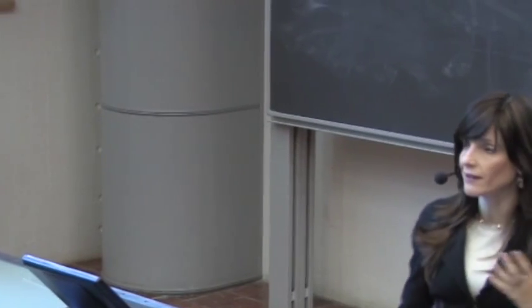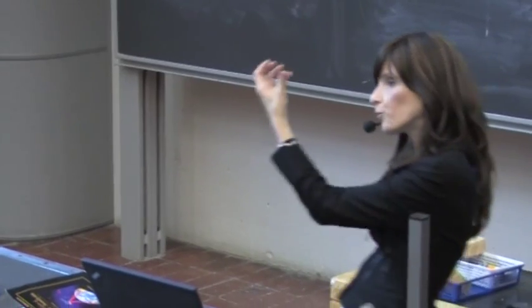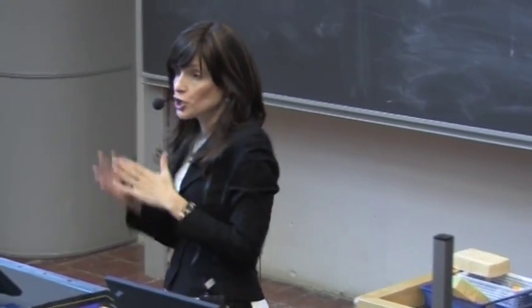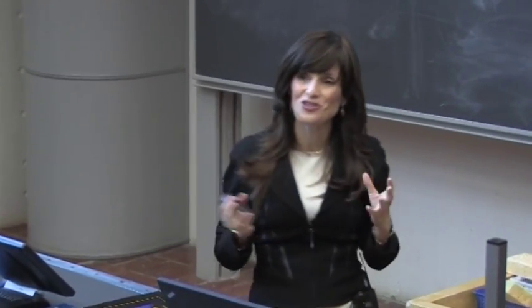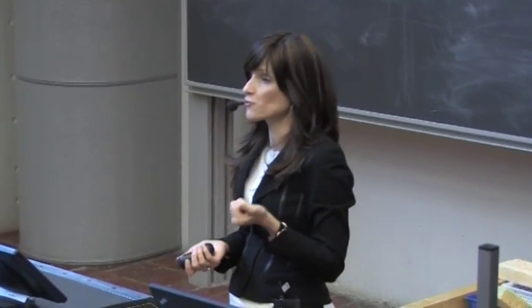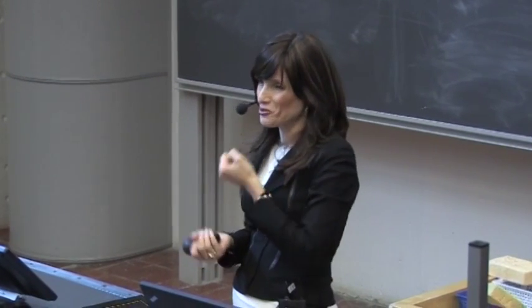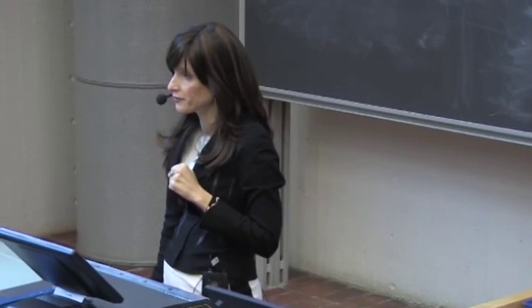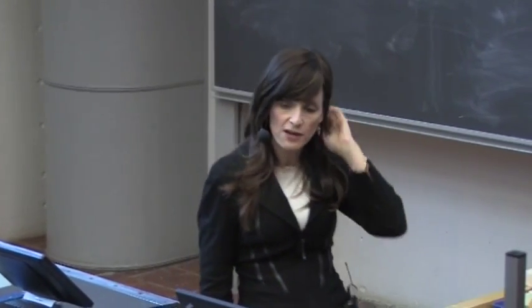And the idea behind cognitive radio is that if we were able to track this wide band and find out where those narrow bands are, then we could exploit these white spaces and use them as long as the primary user does not need them. And of course, there's a huge possibility here for income for the mobile networks, because then they could reuse the spectrum, and of course you will pay very expensively for the spectrum that you're using that you're not the primary user of. So there's a lot of interest here from the FCC and the different mobile networks.